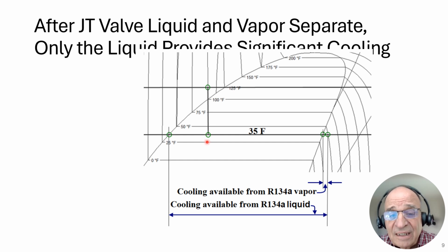Now, is the fluid actually here? No. It comes in here as 100% liquid, flashes to liquid and vapor, and here's our liquid properties, and here's our vapor properties. The point of this slide is to show that as you put this fluid through your chiller, all of, or the majority of, the cooling comes from that liquid, which is changing phase. So you get the latent heat of vaporization, changing phase, extracting heat from the evaporator. The evaporator is sometimes called a chiller.